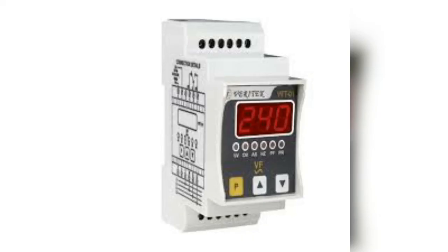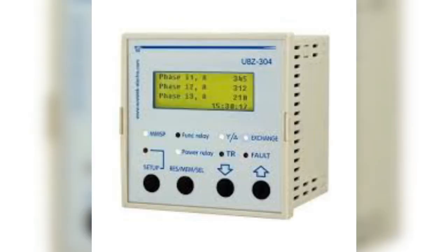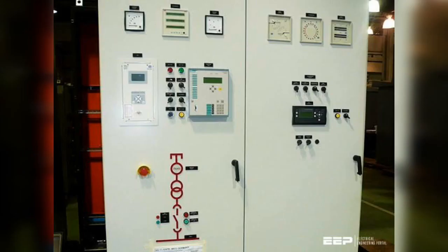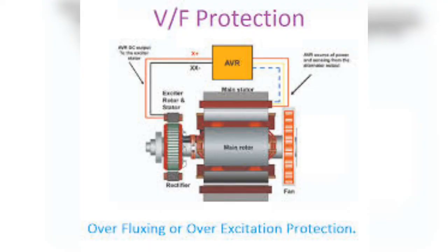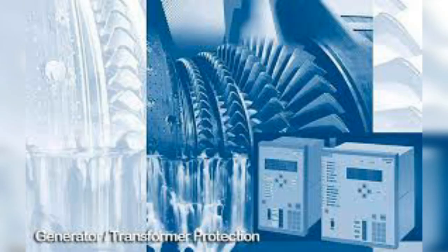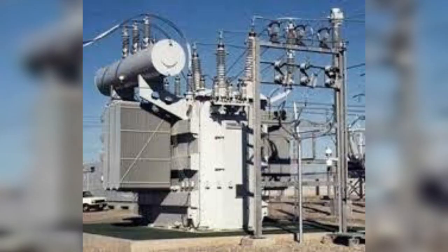The main point of generation starts with an exciter. Most people are thinking about what an exciter is. The main purpose of the exciter in a generator alternator is to provide the stationary rotor magnetic field. It means it is the initial starting of generation, or exciting, which is used to induce the EMF in the armature coil.